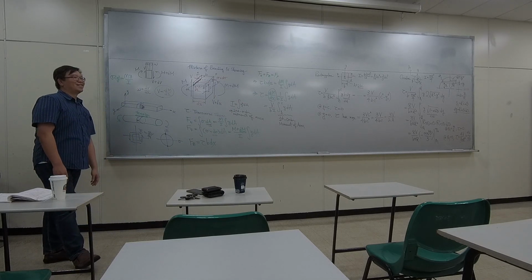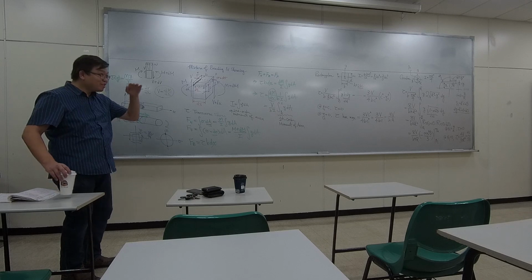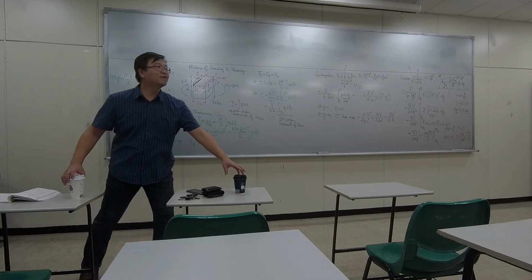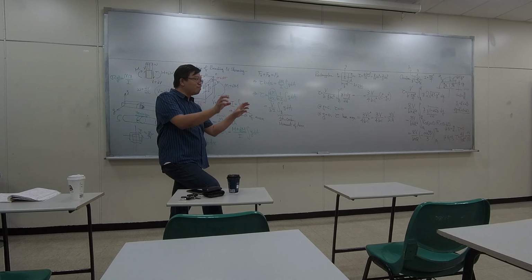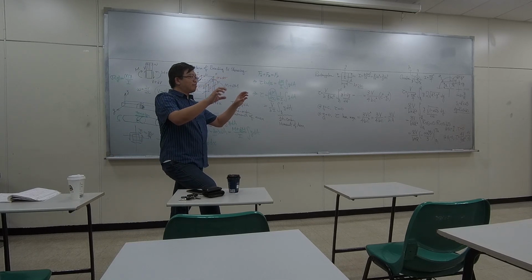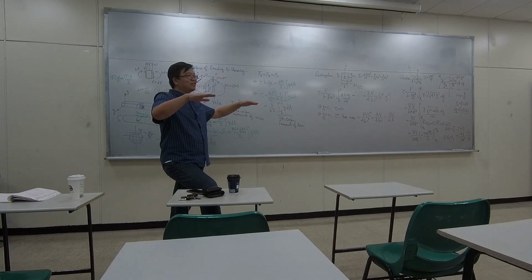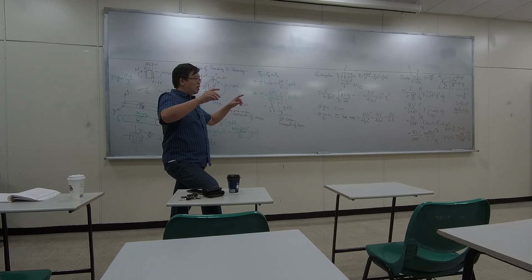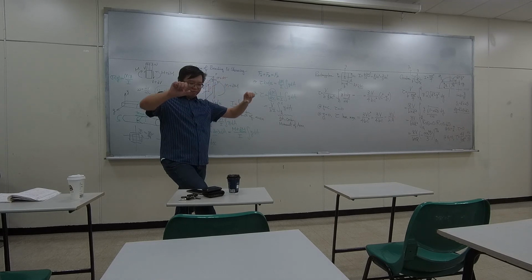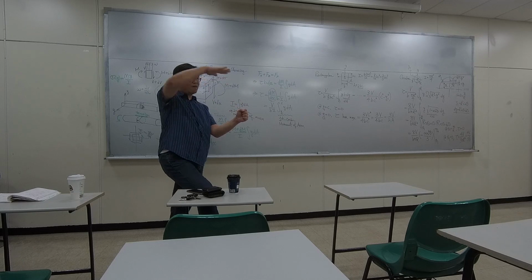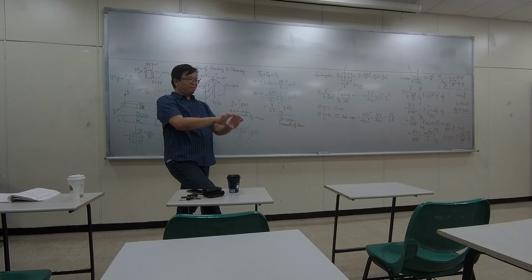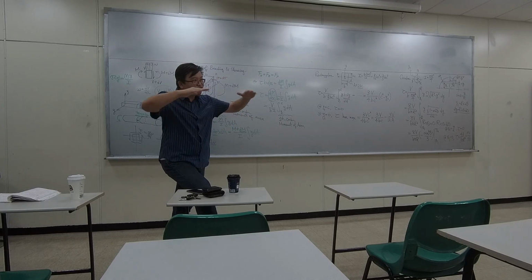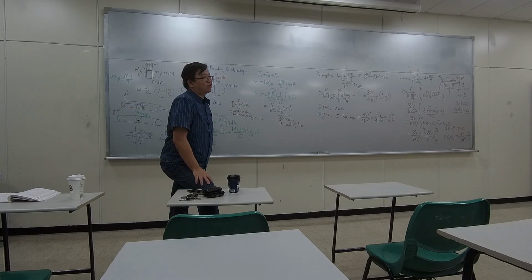Okay. At the middle part. At the middle, yeah. There's only transverse shear or normal. Yeah, because on the neutral plane, if you are doing bending, then the bending only affects anywhere outside of the neutral plane. So the bending generates normal stress. If you bend this like this, on the upper part is like a normal tension force. At the bottom is compression. But on the neutral plane, there's no normal force.